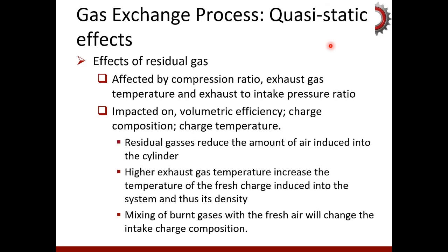Residual gases occupy the space or the volume that could have been occupied by the fresh air or fresh charge. Accordingly, the volumetric efficiency will be reduced due to residual gases. On the other hand, if the exhaust gas temperature is high, then the intake gas will also be heated up. Accordingly, the density will be reduced. And mixing of exhaust gases or burned gases with the intake fresh air would change the intake air or charge composition.